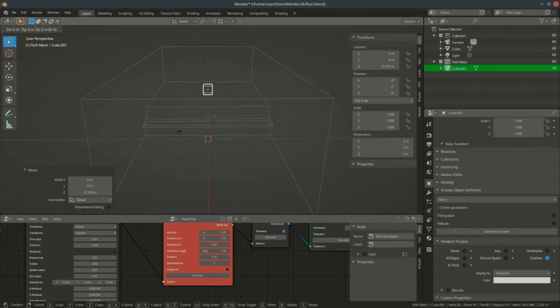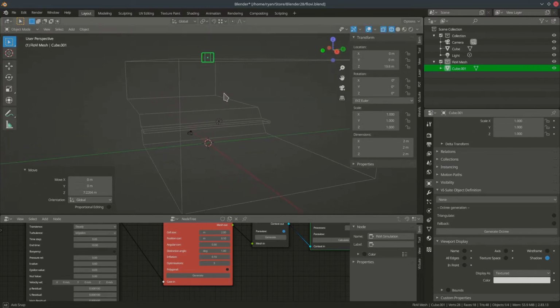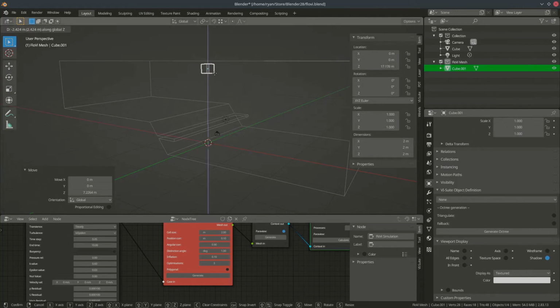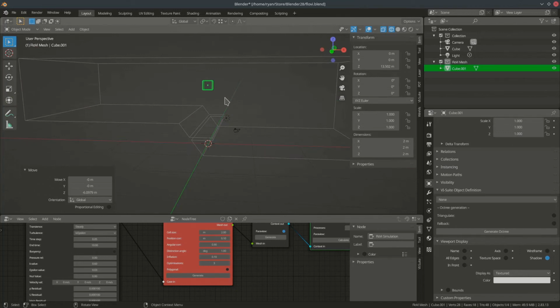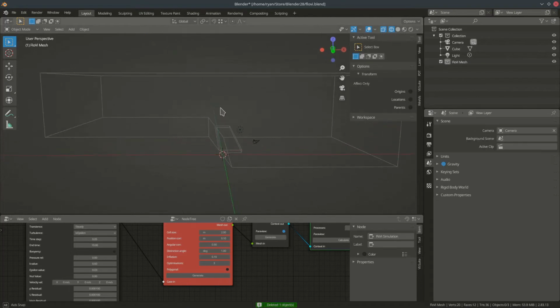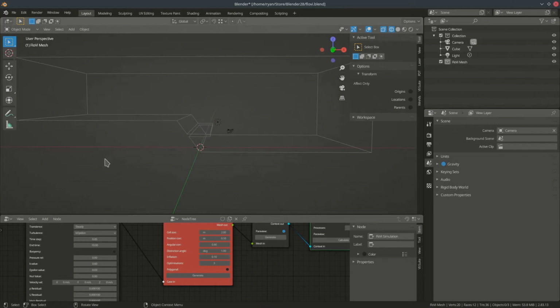But if I was to do something like this, where this CFD geometry straddles the domain boundary, so some of it is inside and some of it is outside, that's not legal. I use NetGen as the mesher, and NetGen, at the time of making this video at least, doesn't allow overlapping geometry. So any CFD geometry has to sit completely within the domain, and then it should function properly. But I'm not going to use that here. I'm just going to do the flow through this ground terrain, which is the bottom of my overall CFD domain.